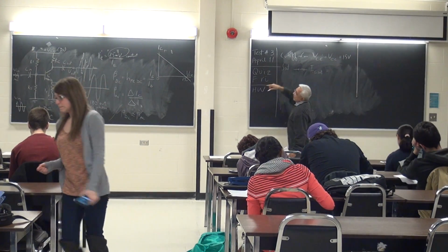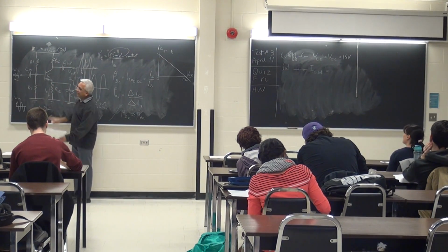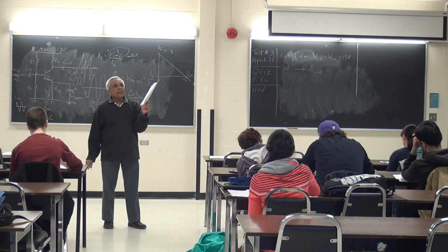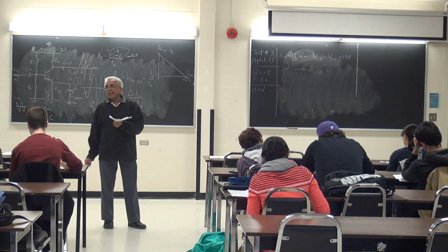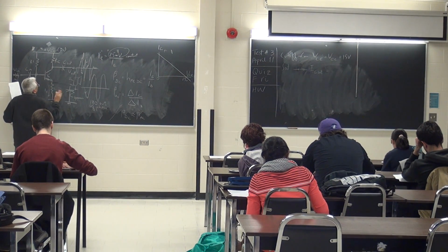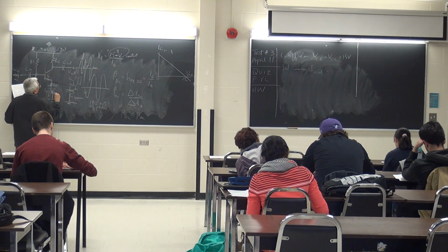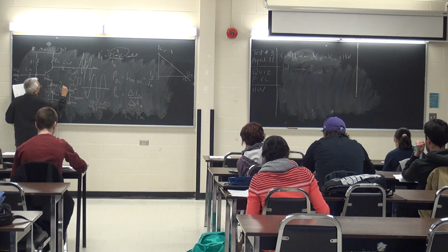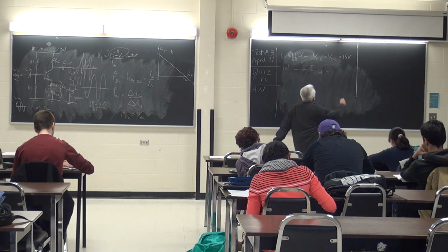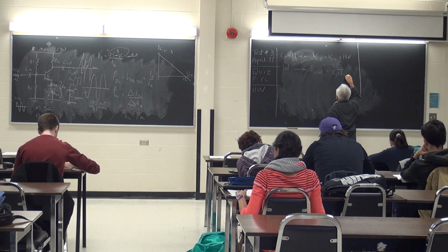is, if this point is going to act like a closed switch, then of that, VCC, RC, and RE. RE in this circuit is made up of two resistors, RE1 and RE2. So both of them together is RE. So can you do that? Can you show this? Right now it's like this, right? RE1, RE2. Can you do this and say RE? So, is that VCC over RC plus RE? Are you with me?